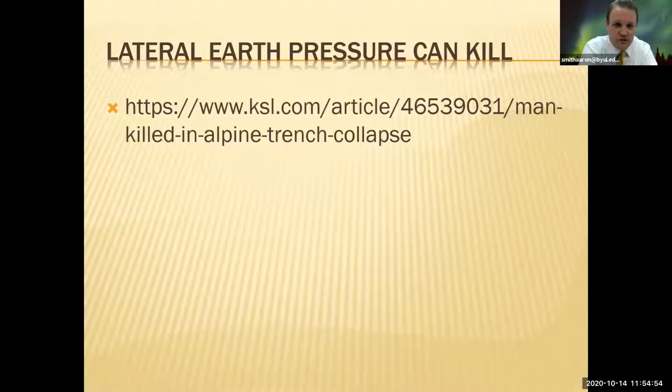Yeah, so let's just do some math. If this guy who was killed was buried by the trench, say 3 to 4 feet of material was coming in on him. Let's say the unit weight of that material was 120 pounds per cubic foot, and maybe there's 4 feet of it on him. He would feel 4 feet times 120 pounds per cubic foot of pressure pressing in on his side. But not all of it. It would be about half, like you said, Josh. So it'd be about 240 pounds per square foot.